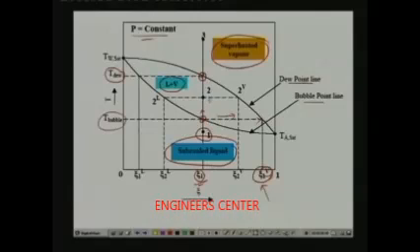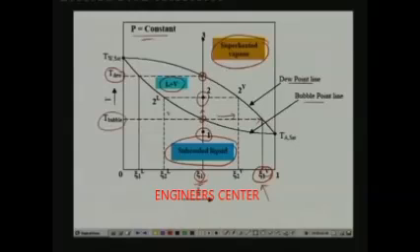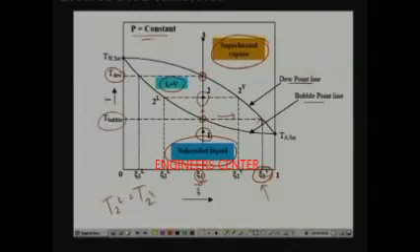And if you look at point 2, where you have liquid as well as vapor, what is the liquid phase concentration and what is the vapor phase concentration? Since both liquid and vapor are at thermal equilibrium, both will have the same temperature. So T2L, for example, will be equal to T2V. Here you have a mixture of saturated liquid and saturated vapor.